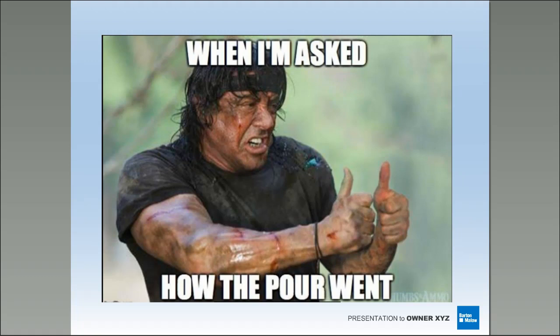Well, depending on what you're looking for, typically we use a lot of steel fiber. We've used multiple brands. Don't really treat it any different. I look at my cut. If I'm going for a sand polish, depending on what my Mohs test tells me and my initial cut, again with the test pour, I'm probably going to start at a 25 or a 70 diamond and then transition out of that. But again, it depends on what you're getting to.